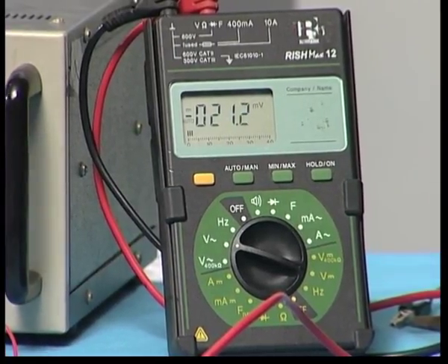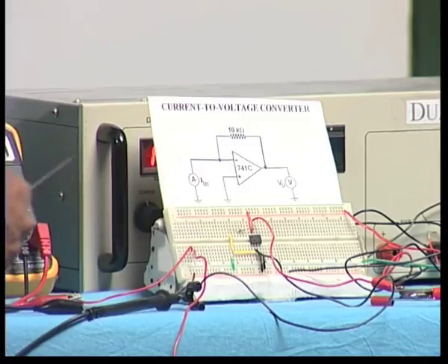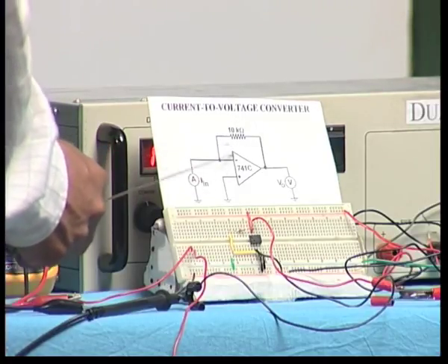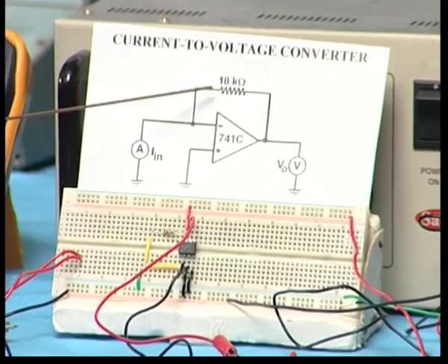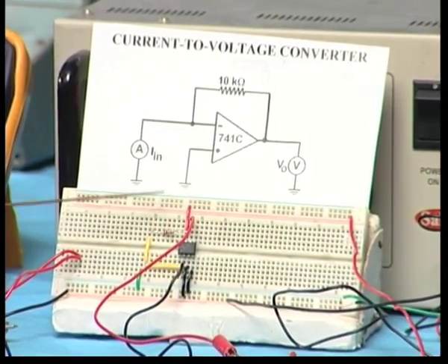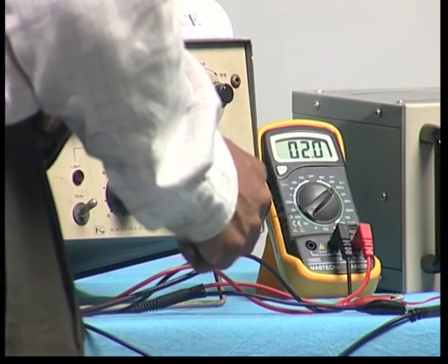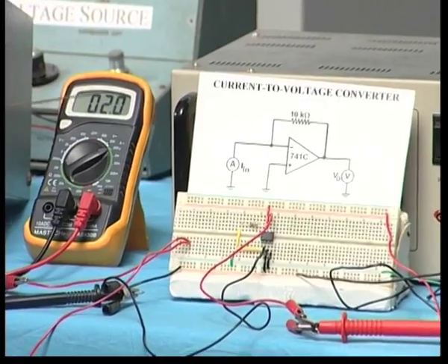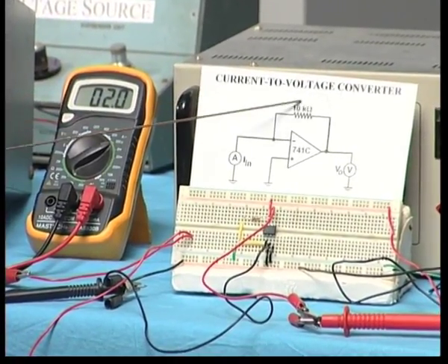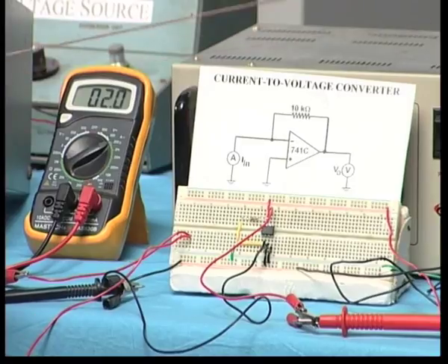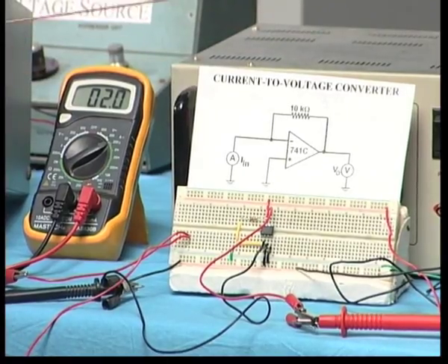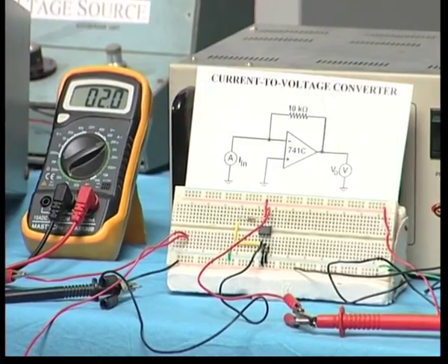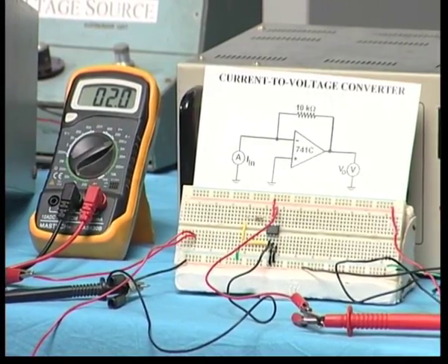So, if I want to change the conversion factor, the conversion factor is basically the 10 kilo ohm, that is a transresistance amplifier. So, if I change it to 100 kilo ohm here, immediately you will find the same current will be multiplied by 100K, and you will get the corresponding output voltage here. So, you can increase or decrease this resistance here and get a voltage proportionally at the output. Therefore, it is a very simple and useful circuit, especially when you have a number of different sensors.